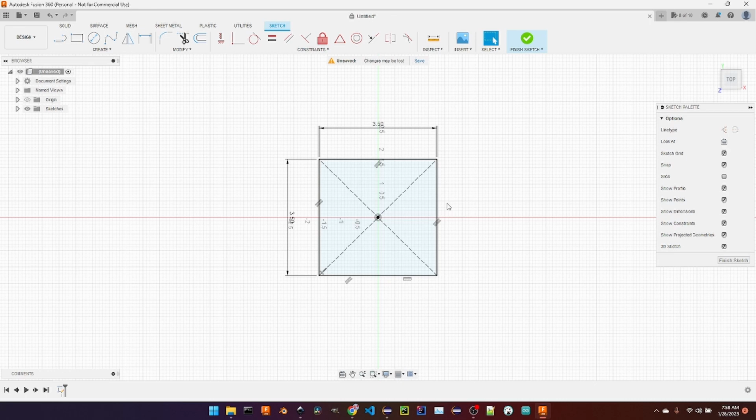You cannot take a fine-tuned SVG and design it on a different object or a different plane. That generally won't happen. For example, if I'm designing this for my lighter, the way I manipulate and change the SVG and this drawing would be a little different than on a piece of wood. So generally I create two separate ones, one for wood and one for metal, and keep them separate because they require more fine tuning. But sometimes it just works. I start with the dimensional drawing so that my manipulation is much less, and I will show you how I do it in both cases.